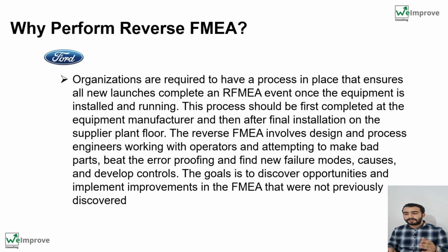The reverse FMEA involves design and process engineers working with operators and attempting... This is the best phrase, which none of the others, let's say, specify. Attempting to make bad parts, beat the error proof, and find new failure modes. The purpose of the reverse FMEA is not only to look at and check the mismatches and the coherence between what is in the process and what is in the documents, but also to challenge and attempt to make bad parts and to challenge your error proof.